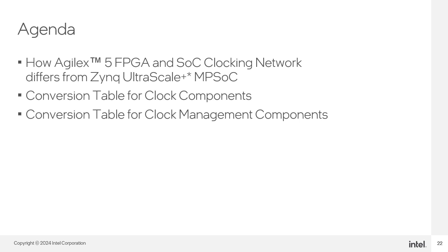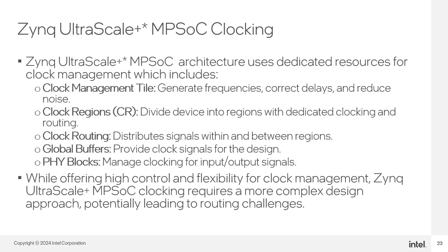Specifically, these conversion tables will cover global clocking primitives, clock buffers, clock management tile components, and Zynq UltraScale plus MPSoC clocking architecture. The Zynq UltraScale plus MPSoC provides dedicated resources for clock management, including the clock management tile, which is responsible for generating the operating frequencies, noise minimization, and latency corrections.